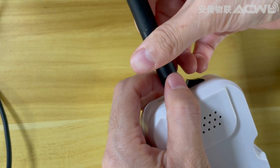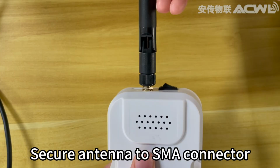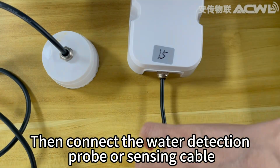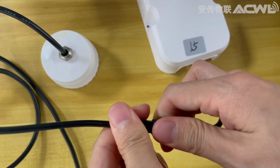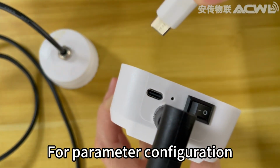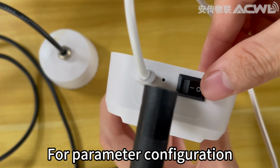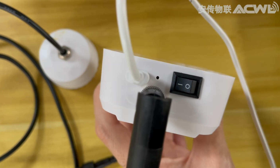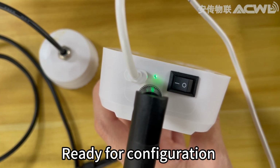Connection procedure. First, connect the 4G antenna. Secure antenna to SMA connector. Orient vertically upward. Then connect the water detection probe or sensing cable. For parameter configuration, connect configuration cable, USB end to computer. Then turn on the power switch. LED indicator solid on. Ready for configuration.